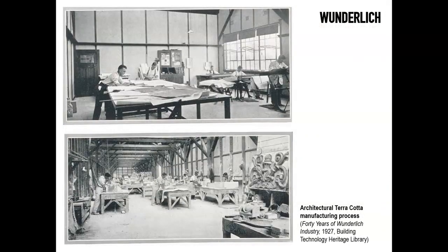In parallel with that, Wunderlich would have a technical department that was able to produce shop drawings, so take architects' drawings, look at the design intent, we would say, and then produce shop drawings exactly like you would do today with facades and many other trades, where the manufacturer, the subcontractors take on board the design, but they are the ones who document and develop the details for production, but also are able to have an input in the detailing so that you can understand how to put things together.